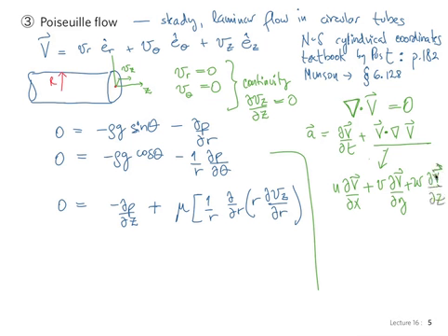So it contains the spatial derivatives, and it represents the convective acceleration, the change in velocity that a particle of fluid experiences just because it moves from one place in the fluid to another place in the fluid. If a particle were to instantaneously teleport from A to B, its velocity would change because v is different in all points in space. And this is what we call the convective acceleration.